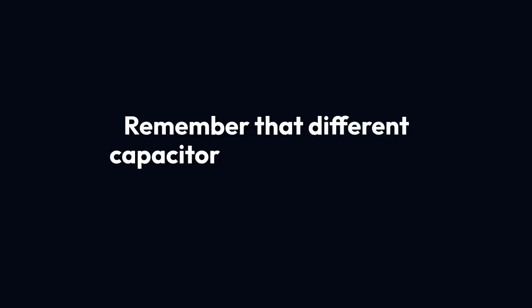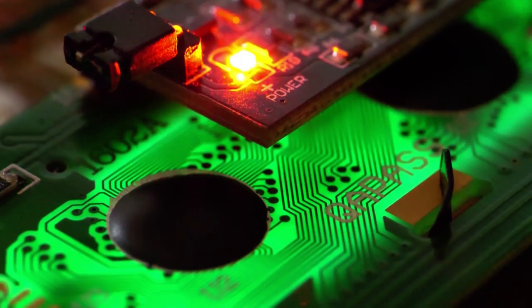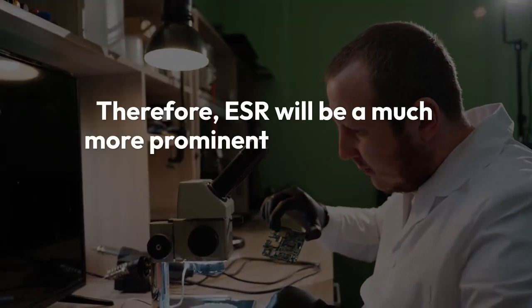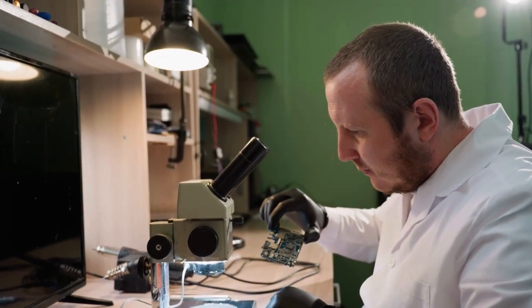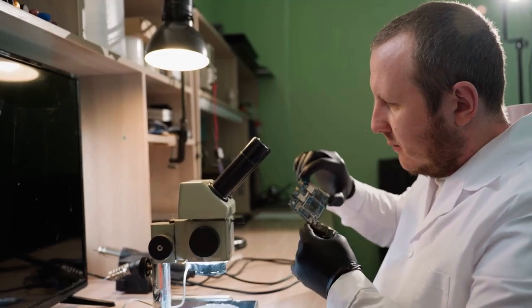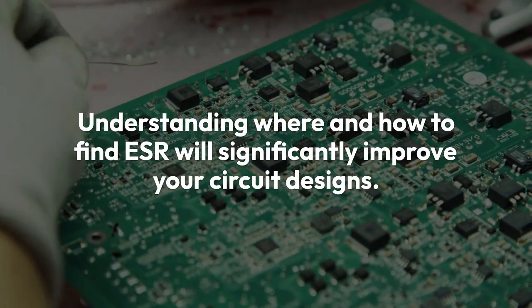Remember that different capacitor types have vastly different ESR characteristics. Electrolytic capacitors generally have higher ESR compared to ceramic or film capacitors. Therefore, ESR will be a much more prominent specification in an electrolytic capacitor's datasheet. For ceramic capacitors, ESR is usually so low that it might not be a primary concern and could be harder to find explicitly stated. Understanding where and how to find ESR will significantly improve your circuit designs.